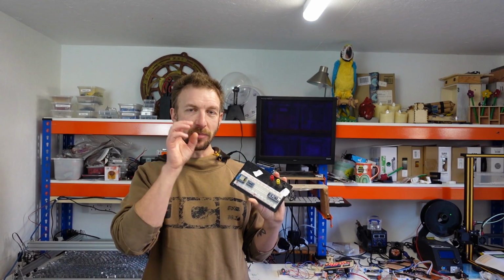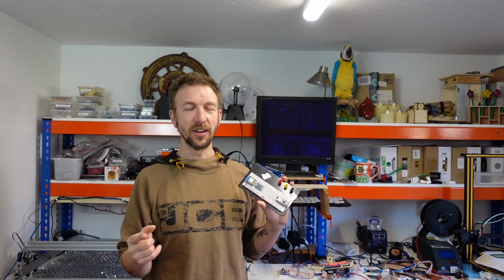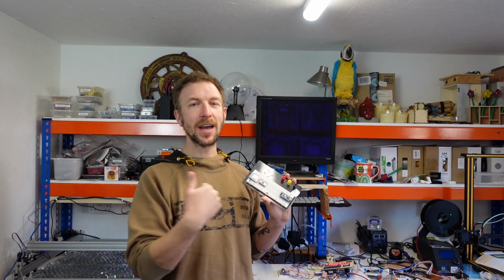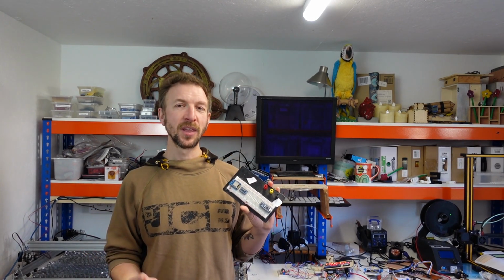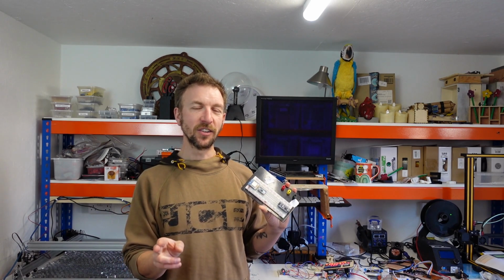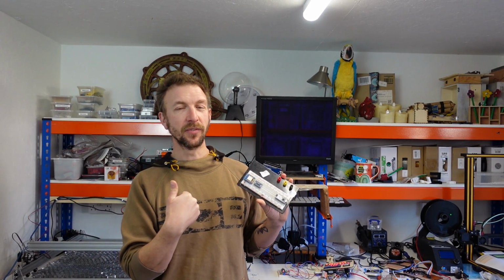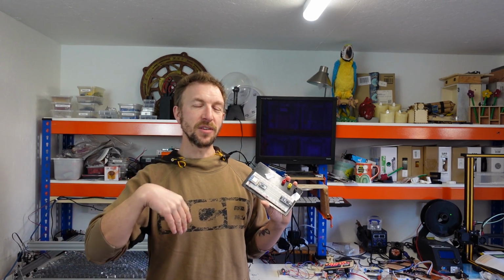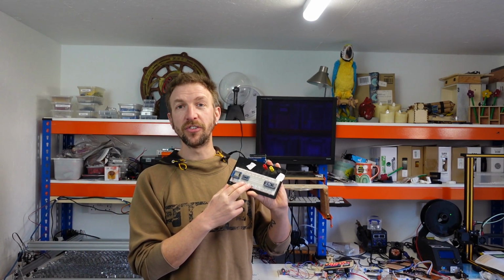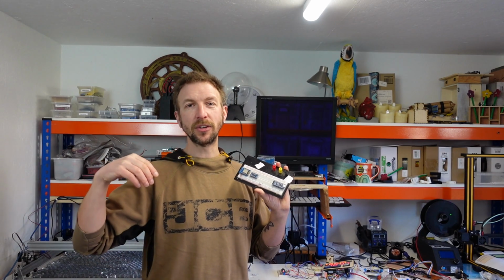So rather than, at the moment I'm using a single wire connection, and that is both transmitting and receiving between all the devices. If I had a 2-wire connection instead, so a transmit and a receive, what I could do is on the receive line of a 3.3 volt device, step down the 5 volt signal just using a pair of resistors. So let's say I've got a 5 volt signal coming in.